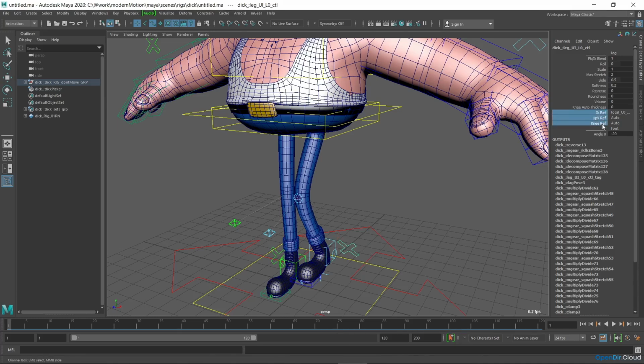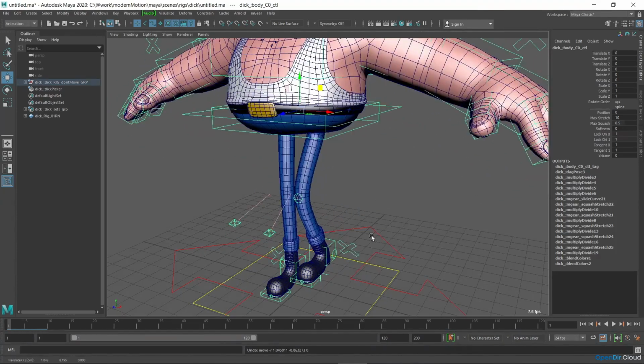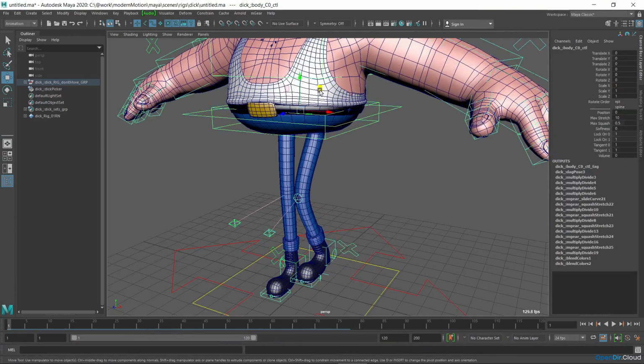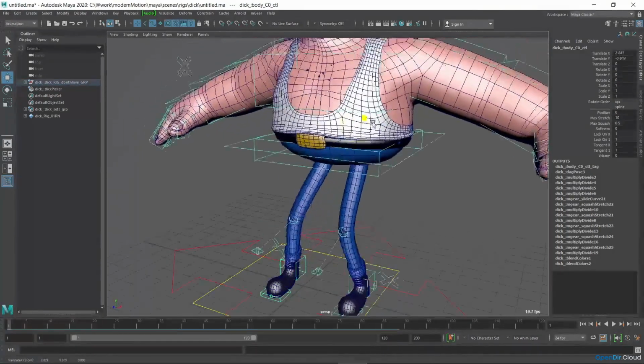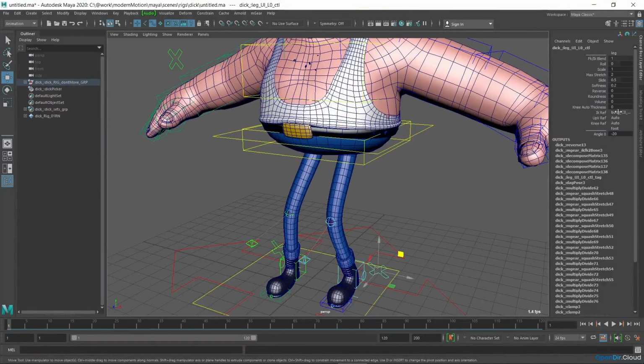Reference attributes for the foot controllers of up vector and knee, namely IKRef, UpVref, KneeRef, allow you to switch the parents of the respective controllers, which were specified in the guide properties when building the rig. By default, the IK leg controller inherits the transformation of the local controller and is body independent. If I change the IK_ref attribute to body, you'll see that the leg will inherit the body.